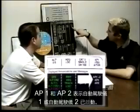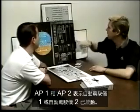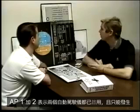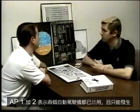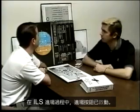AP1 and AP2 indicates that either Autopilot 1 or Autopilot 2 is engaged. AP1 plus 2 indicates that both autopilots are engaged, and that can only occur during an ILS approach after the approach button has been armed.